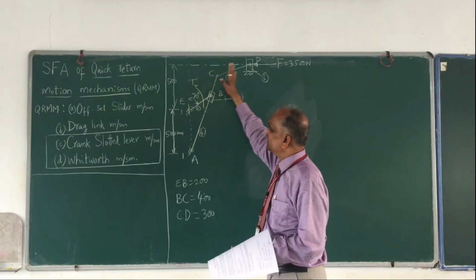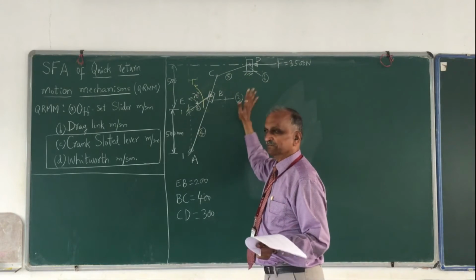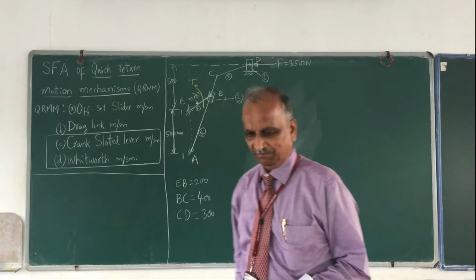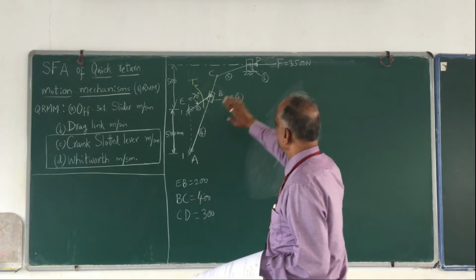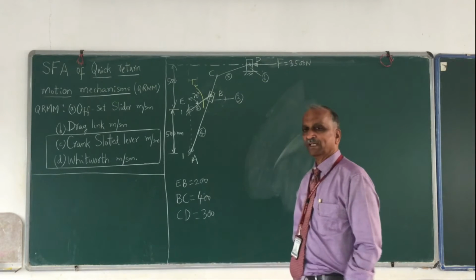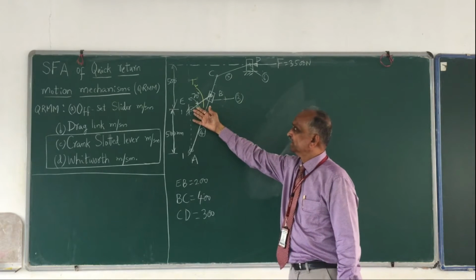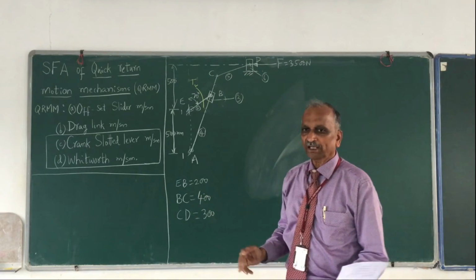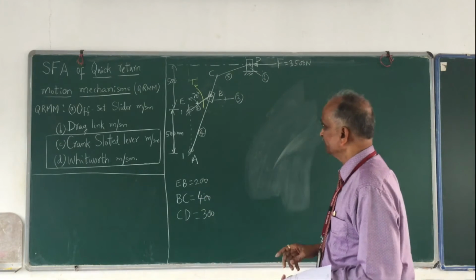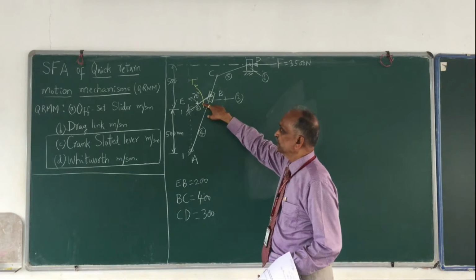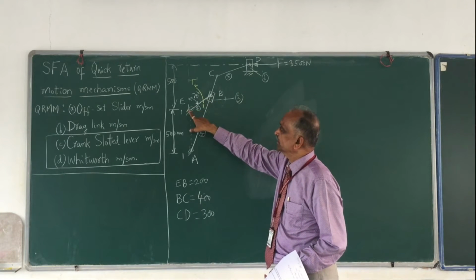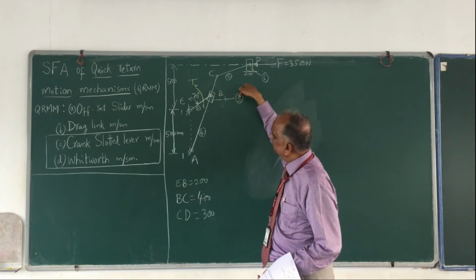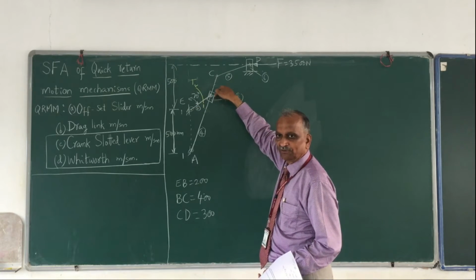These values may change, but the problem in the examination will remain the same. So follow the same procedure: go through all the mechanism, all the links, link 2, link 3, link 4, link 5 and link 6, and identify where you can start. Link 2 has a torque and one force F12 and another force from link number 3, F32.